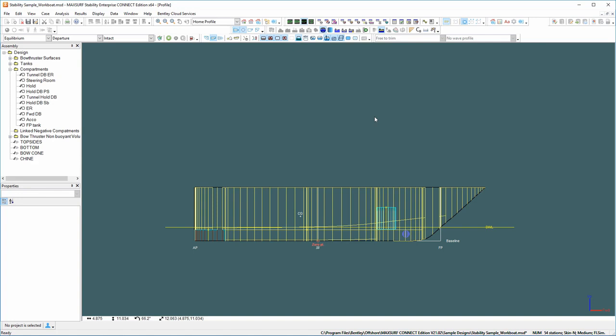You cannot get the VCG higher than what you find in the limiting VCG case. So it draws a very firm line in the sand that you can use with the other engineers as a do not exceed weight and height.